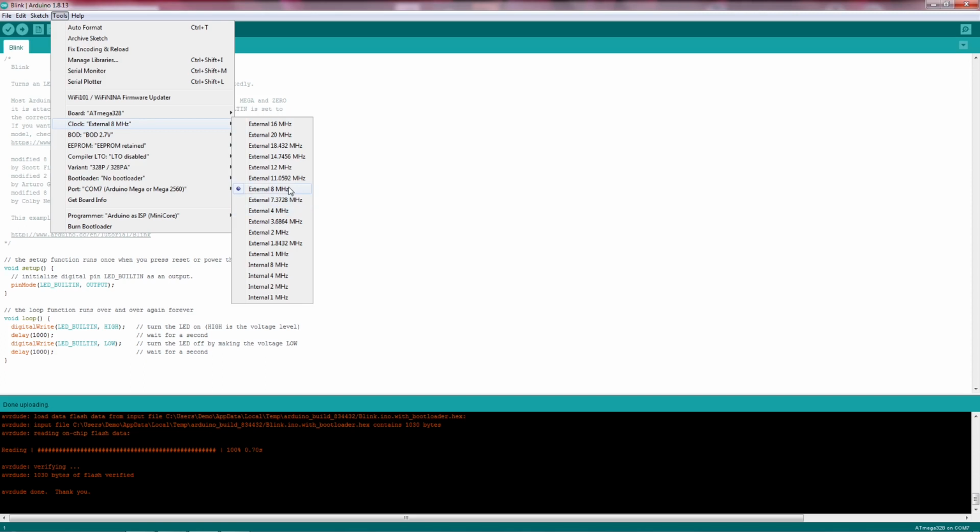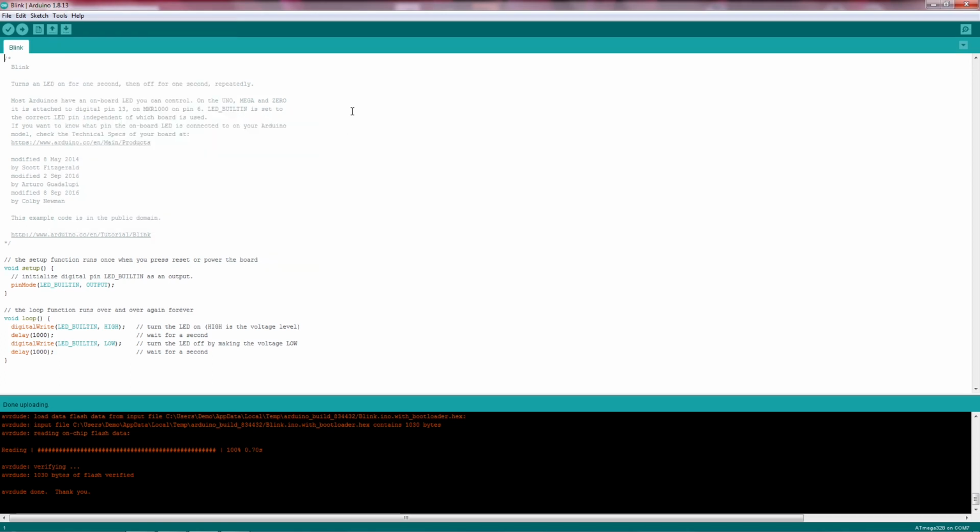You should have it set to the same configuration from here onwards if you're using this microcontroller. And if you change microcontrollers, you have something else that's running at 16, okay, then you set it to 16, right? You don't need to burn the fuses. The crystal defines the 16, but you do need to do it here because of compilation. Why?